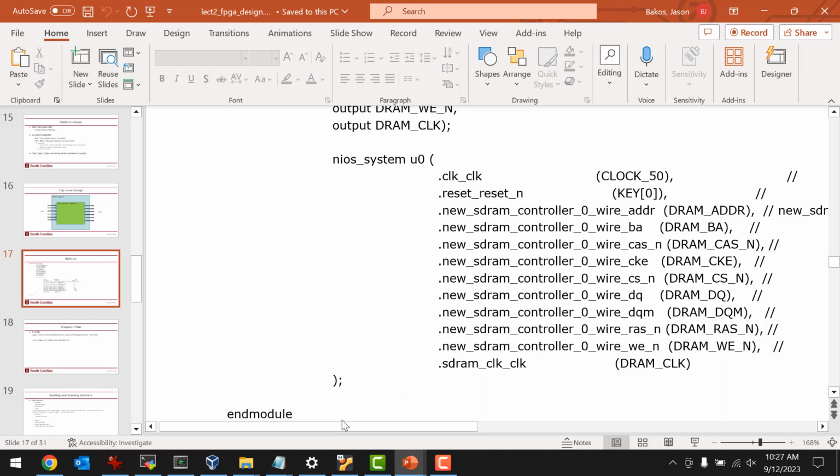Again, I don't know exactly how that works, but JTAG has the ability to test the FPGA, to configure the FPGA, to put the bit stream in, to pull out certain registers, and UART. It carries the UART signal on top of the JTAG bus, and then ultimately through the USB bus back to the computer.